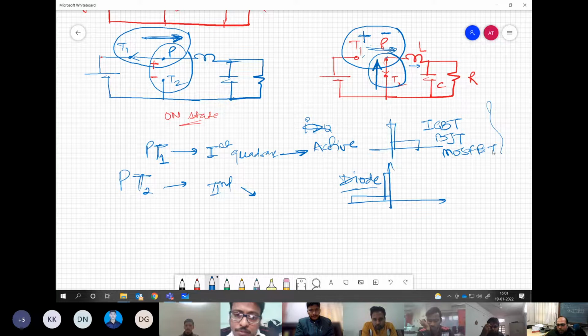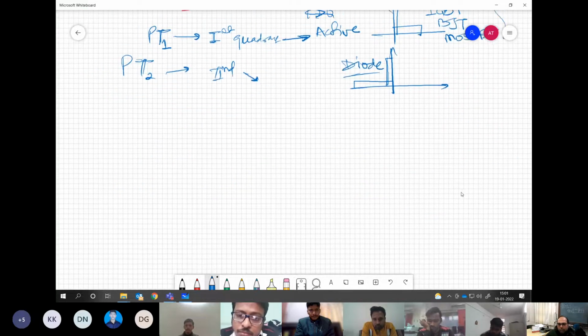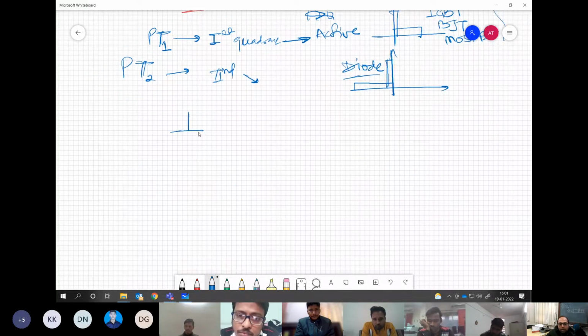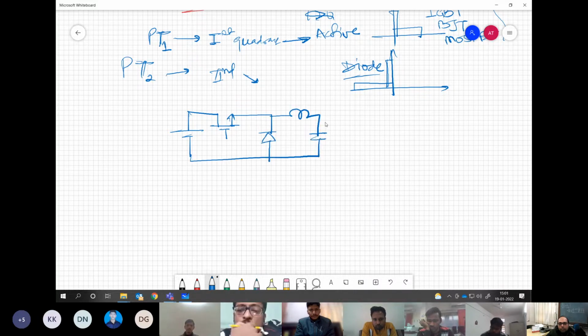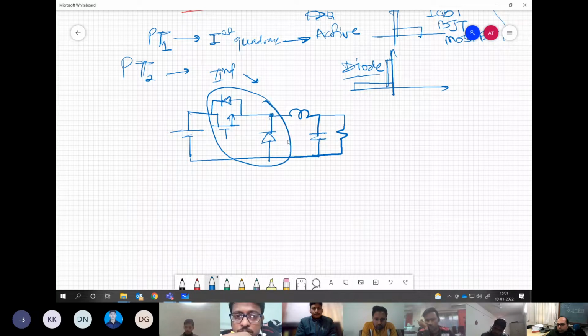So that is how we realize the famous buck converter circuit, which is something like this. Because it is a MOSFET, I have drawn the body diode. Otherwise, this is actually not necessary here. Correct? So, hence, we get this combination of switches for the buck converter.